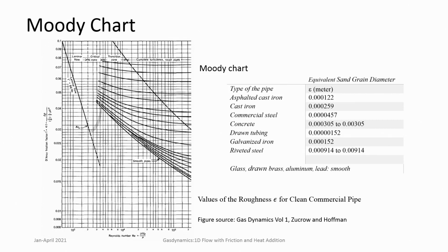So, from here we understood in a qualitative sense what is happening in Fanno flows, and there are differences in how the flow behaves in subsonic flow and supersonic flow, with the point Mach number equal to 1 being the critical point, where entropy is maximum. Now, in the next class we will look at getting equations in terms of Mach number, so that terms such as pressures, temperatures, and change of Mach number can be evaluated in a flow through a constant area duct with friction.